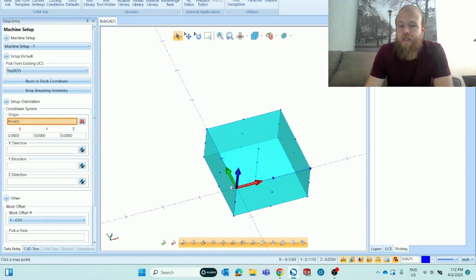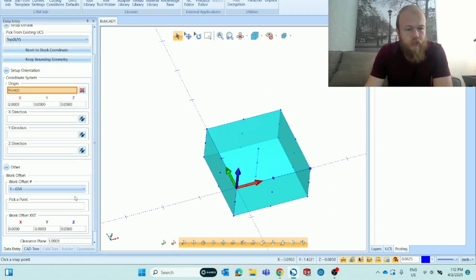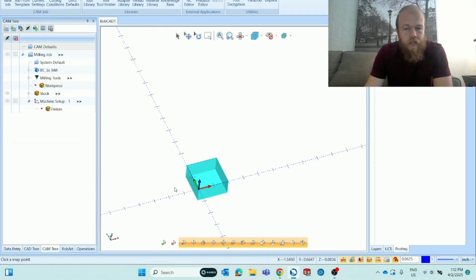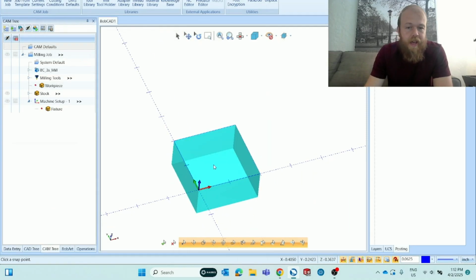So when we look at the G-code coordinates from my G54 reference point here, this is going to be X0, Y0. And for an example, the tool is going to come down and then it's going to move across to X2, Y0 here. And then it's going to move up to X2, Y2 and then move around the rectangle. So we'll click OK. And we've got everything set up for CAD and CAM now.